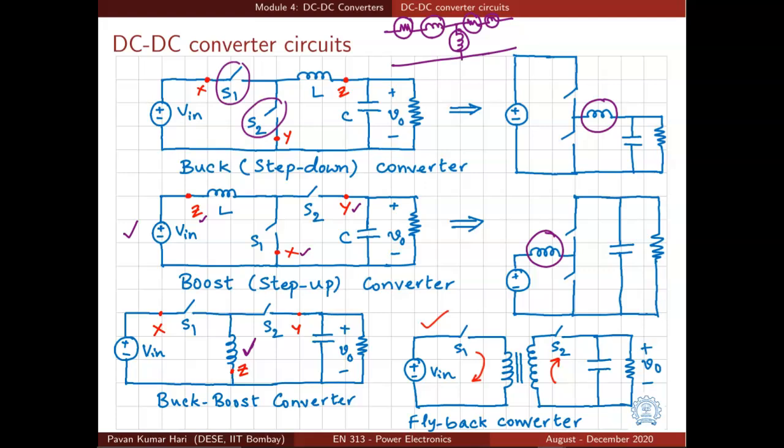There are many types of dc-dc converters that are being used in a variety of industrial applications. So what is the difference? Let us say we have an application in which we need to choose a particular dc-dc converter to perform some kind of step down or step up or inversion of polarity, some function. For that we have two or three kinds of options. For example, you take buck and buck boost. Buck boost can also do the step down operation. Buck converter can also do step down operation, right? So how do we choose that? We choose it depending upon the performance.